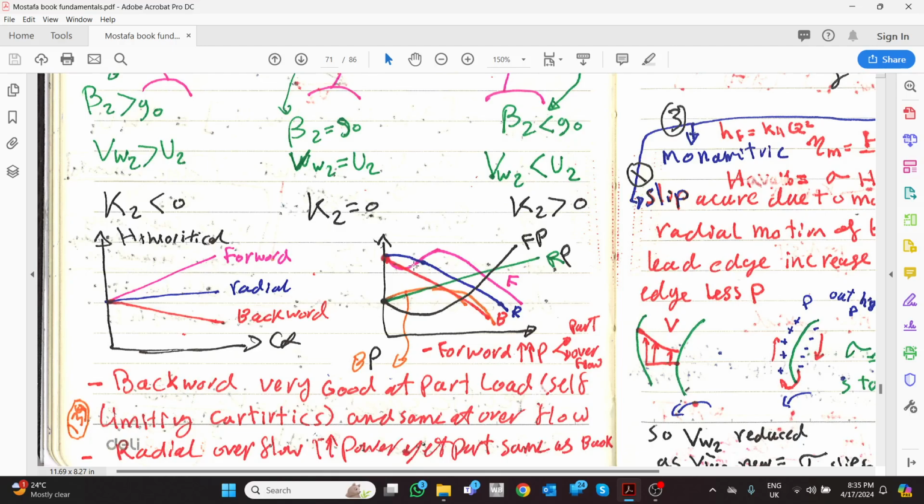But if you are coming from here, from low pressure going up, the pressure required is more to run more flow, which creates a high pressure after the pump, which will create a back or a reverse flow. So that's why even in the fans, we never select before this, we never run before this one. Always we are going to run here because we don't want the reverse flow.